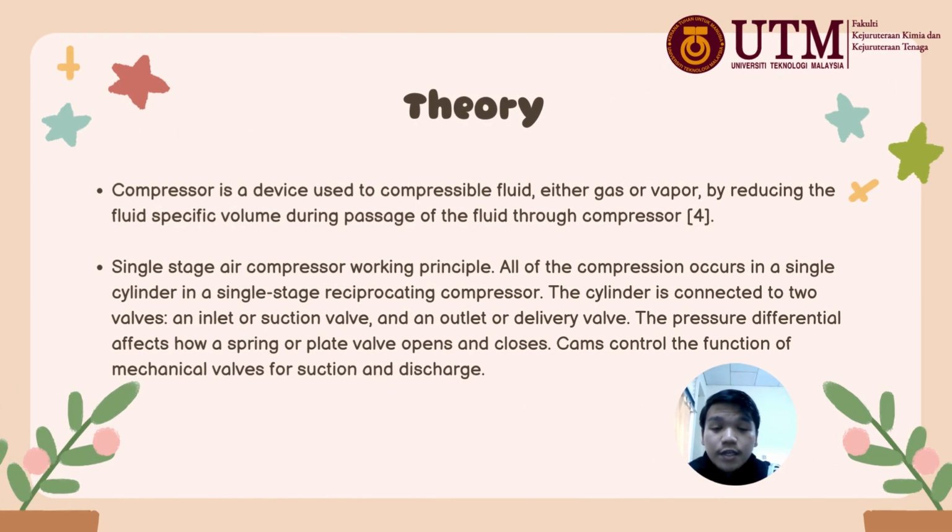Now I will explain about the theory. So what is actually a compressor? A compressor is a device used to compress a compressible fluid, either gas or vapor. But how? By reducing the fluid specific volume during the passage of the fluid through the compressor. Single stage air compressor working principle: all of the compression occurs in a single cylinder in a single stage reciprocating compressor.